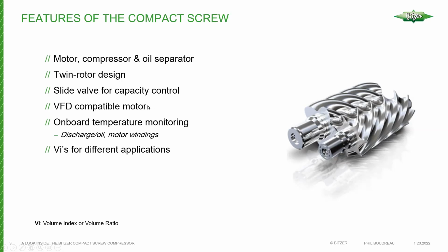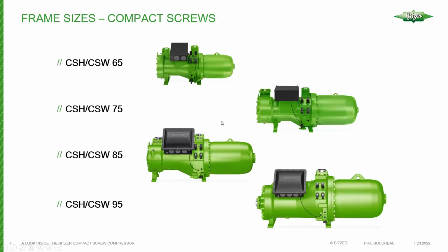The fact that the motor is VFD compatible. In fact, this is really the case with all of the BITZER compressors. They all have a VFD compatible motor built in. Onboard temperature monitoring is really to monitor your discharge and oil temp, and also the motor winding temperature, just to ensure that something's not going wrong in terms of single phasing, motor overload, or what have you. These compressors are also available with different VIs for different applications, which I'll talk about in a few minutes.